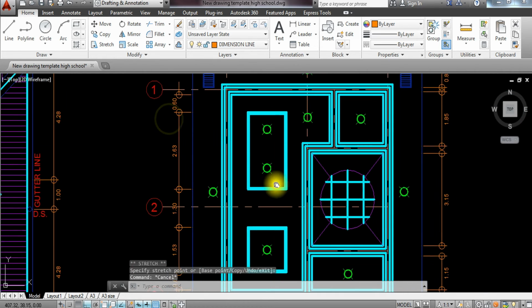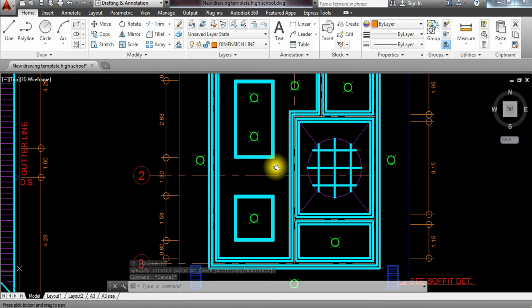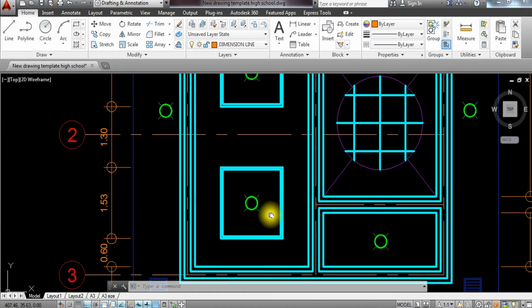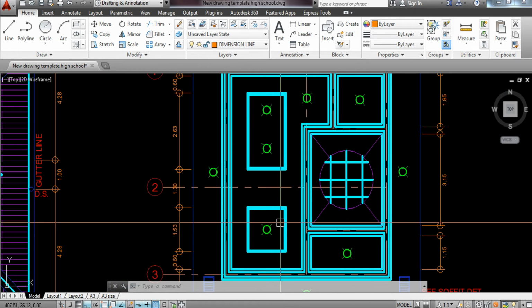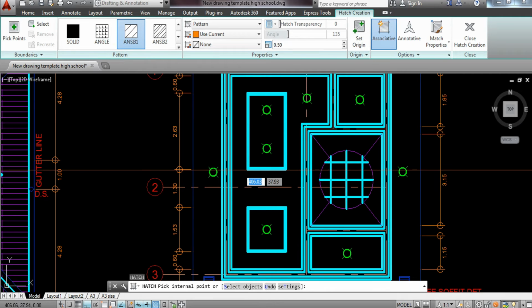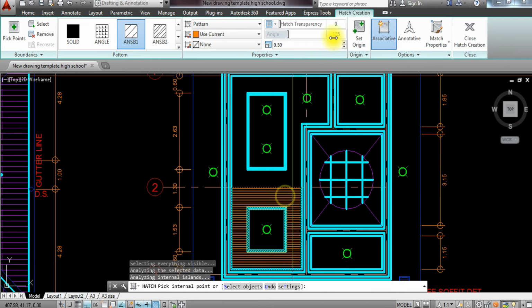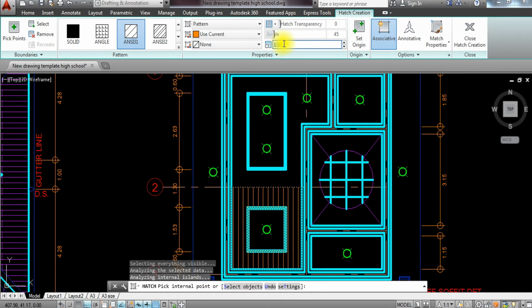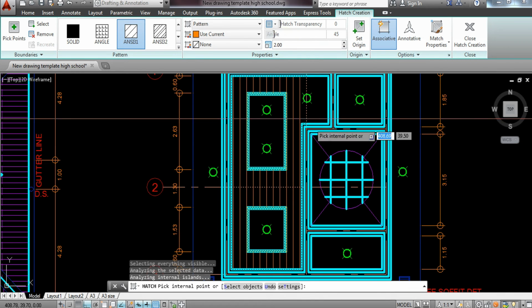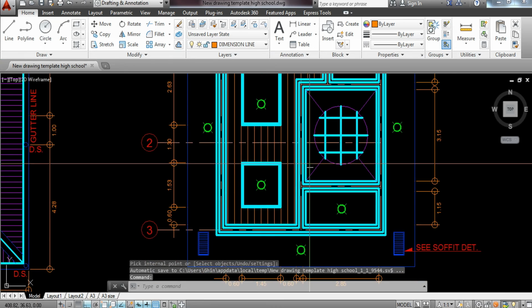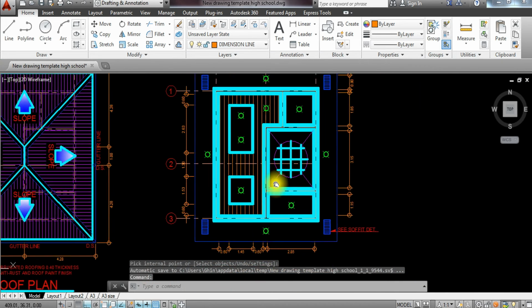Now, some, they are using hatching methods. For example, dito. So, some of the designers, they use hatch method. So, I'm going to use hatch here, which represents wood or PVC wood panel. I'm going to type 45. And then I'm going to increase the size by, say for example, 1.5. Okay, or even 2. Okay, 2 as a representation of wood panels, okay, or what we call PVC panels.